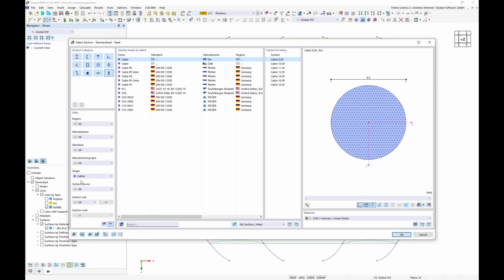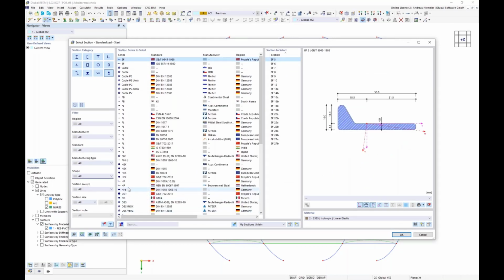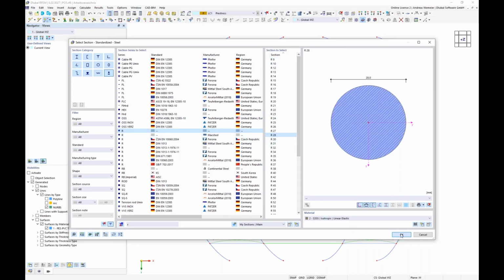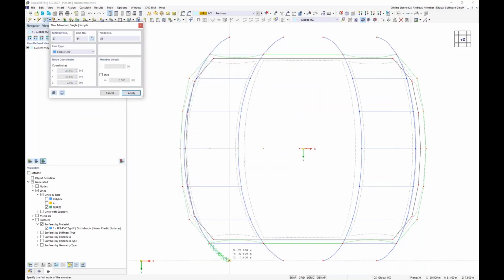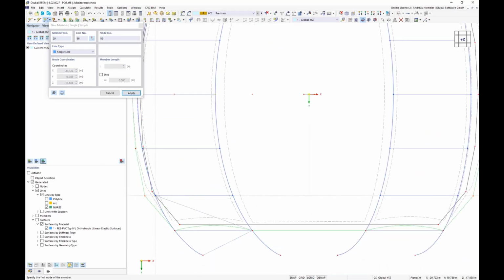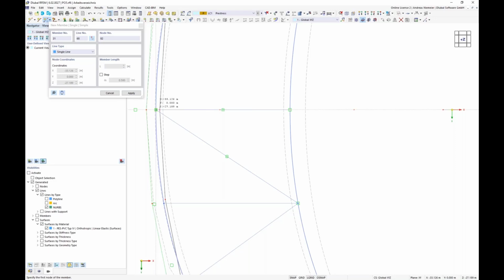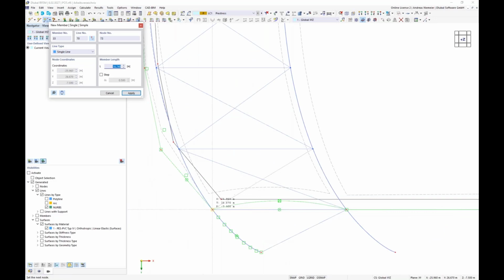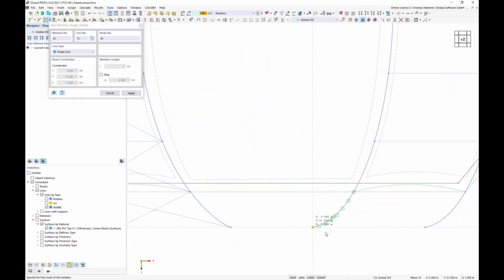I can use a small cross section which has no big bending stiffness. So I use here a circular massive section, for example with 28 millimeters from this steel, and now pick these bracings into these cells. Now this is the top ridge, and again here downwards, and now here's this eave point and foundation point. Now the same on the right side.